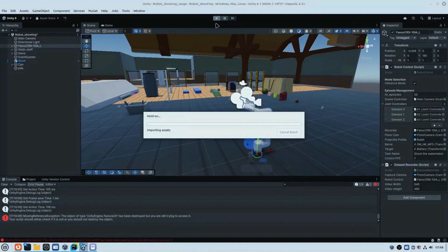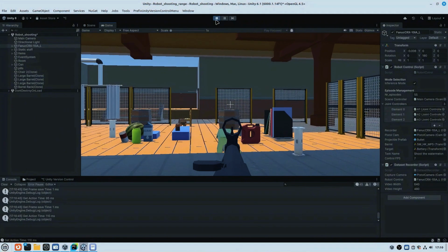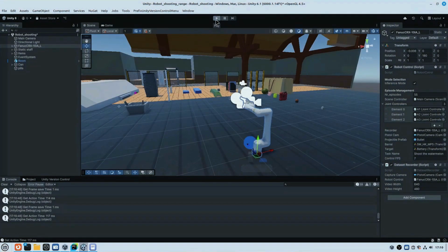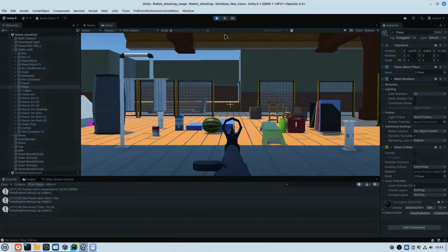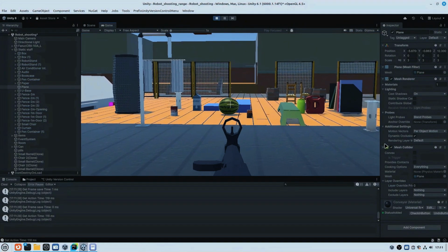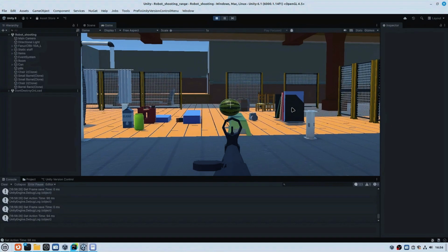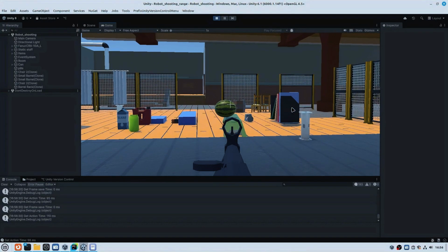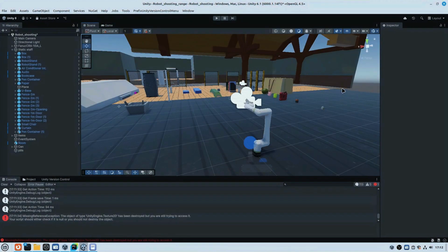Okay, so I think I found the reason for that unstable movement and made something to improve it. Now our SmolVLA is quite stable after I reduced the control FPS from 10 to 7. Now you can also see the movement is smoother, because now there is enough time between action requests for SmolVLA to process, calculate a new action and send it. The reason was just too frequent updates, and our computer wasn't able to generate new actions on time. Now let's calculate our stats again.